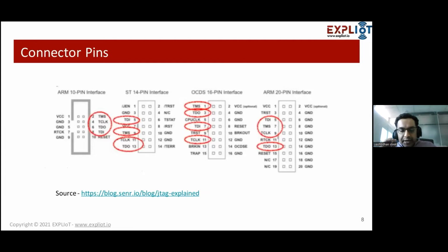Now, when we start thinking from this perspective, if I want to hack into those kind of products which have the JTAG ports, as you can see, the list of different processors or controllers have these pins over there, right? So it means that they are JTAG enabled devices. Even in the AVR architecture, if you start from the very basic ones like ATmega 8 and ATmega 16, they did not have that JTAG capability. But from the ATmega 32 onwards, like even the ATmega 328P, which is generally used in the Arduino kind of stuff, they have this JTAG capability.